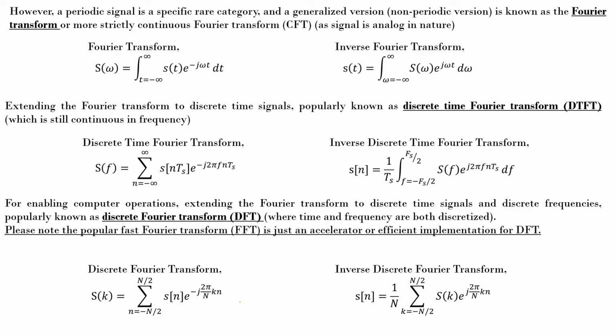Okay, so that's it. I hope it's pretty clear to you, but don't forget the underlying major principle, which is nothing but this: the Fourier transform means you have a bunch of sinusoids. The sinusoids are nothing but sums of sines and cosines. They vary in frequency, and each Fourier coefficient corresponds to a frequency waveform, and you are correlating your signal with that waveform, finding the correlation value, and then you put it there. That is what the Fourier transform is all about.